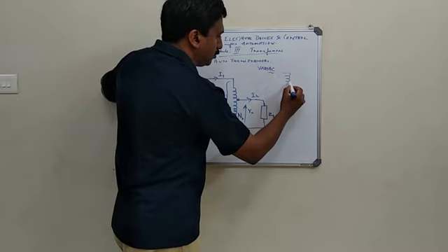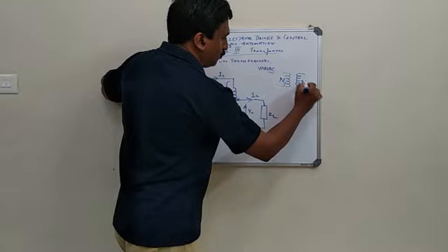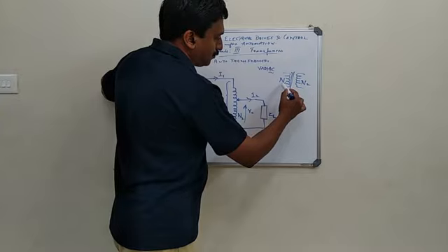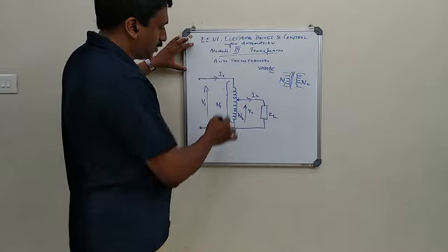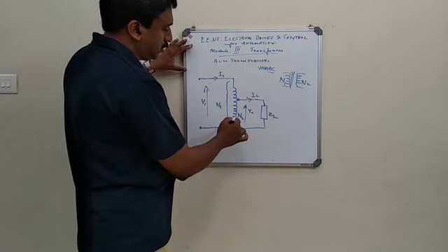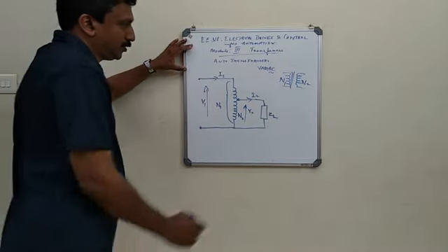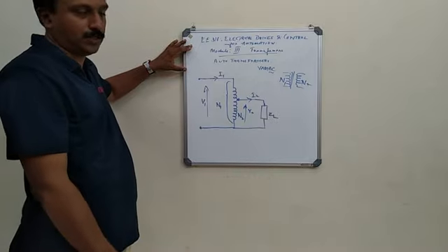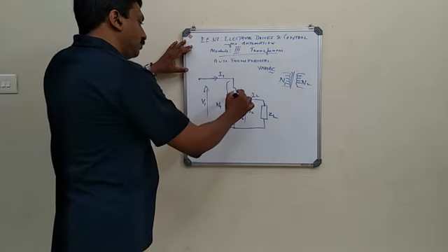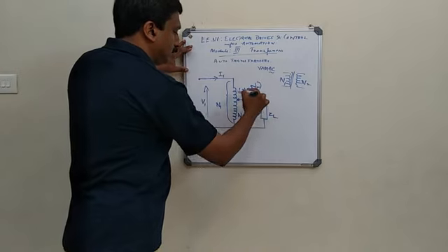So in a two-winding transformer, you have this N1 and N2 on an iron core. There are two lines in that case. So this N1 and N2 are separated, whereas here you can see that this N1 and N2 are actually forming a part of the same continuous winding. So there is no electrical separation. Here that is continuous. So this is N1 minus N2 number of turns here.